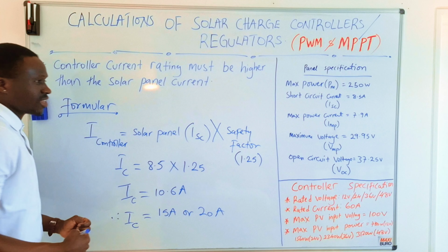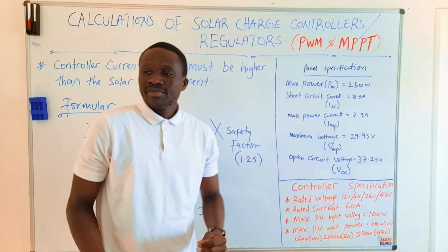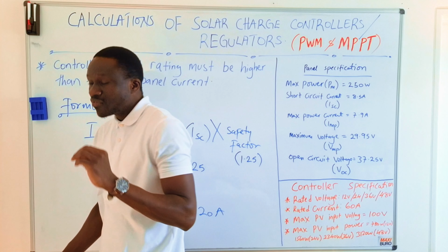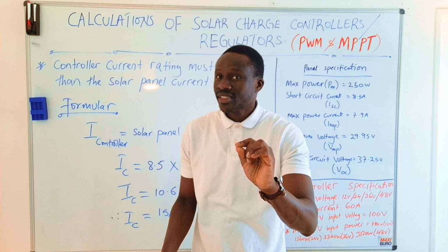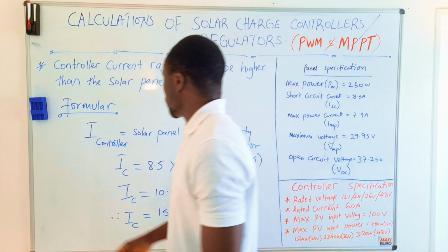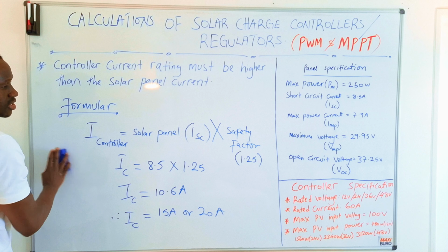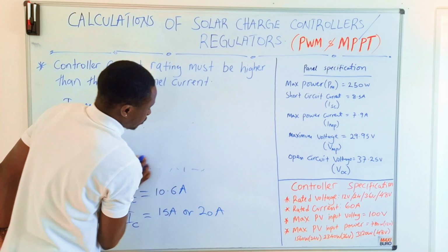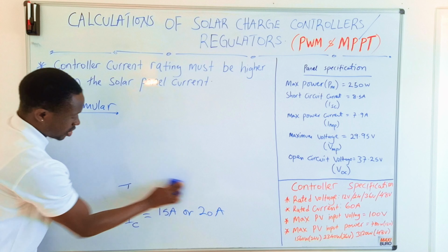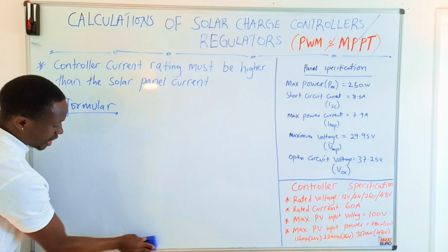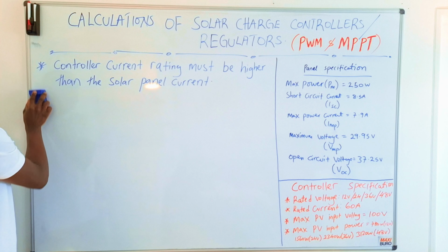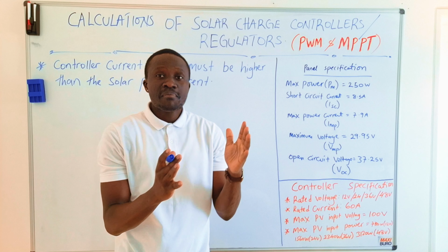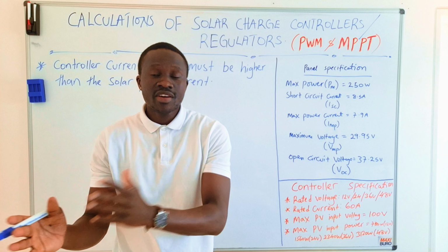Okay? And remember this. The controller voltages must match. Okay? Let me give you this hint. I know you have got some writing about this. Let me give you the hint about a charge controller. A charge controller's voltages must match with the battery voltages.